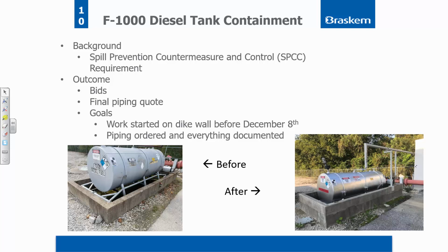Okay. So inside pipe leaks. I don't want it going on the ground. Outside pipe catches it. It's sloped to go all the way back to that tank and drip inside the containment. That way, if it drips, it doesn't drip outside. And on the other side of that fence, anybody know what that is other than the property line? What's on the other side of the fence? The river. Good job. Diesel fuel in the river is bad.